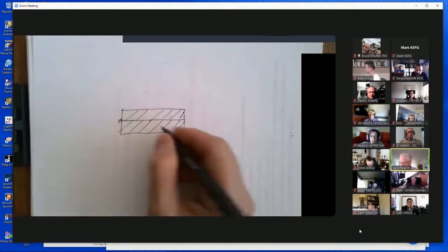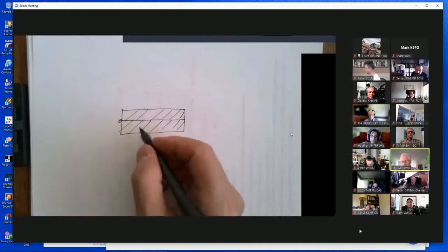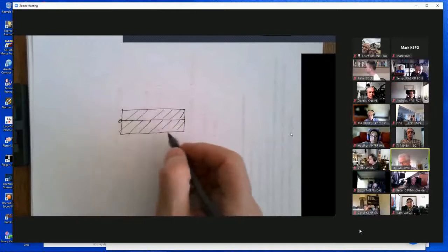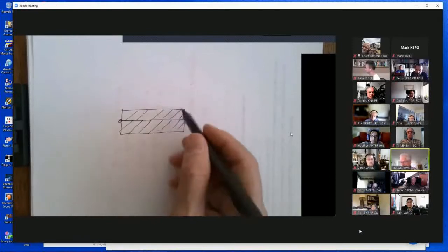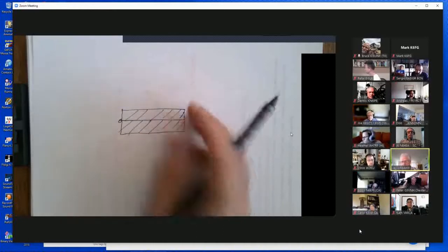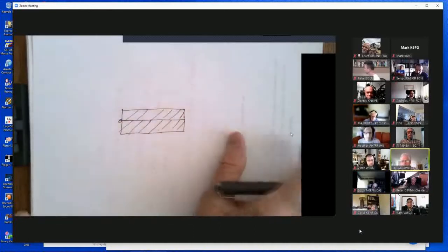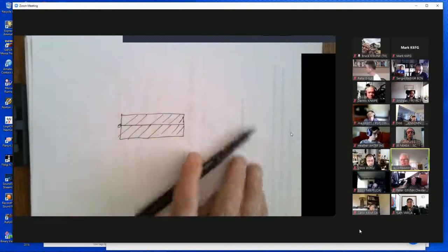However, you're still running into certain laws of physics. It will work as a shorter antenna. Problem is you're still running into that I times length, and the radiation resistance is not there. It works, and your cell phones use it.